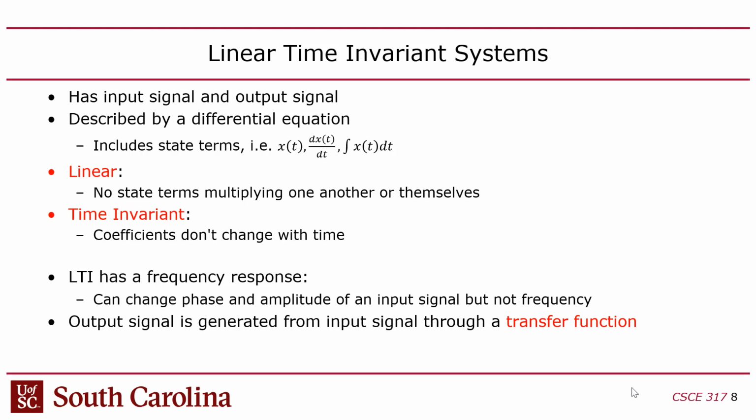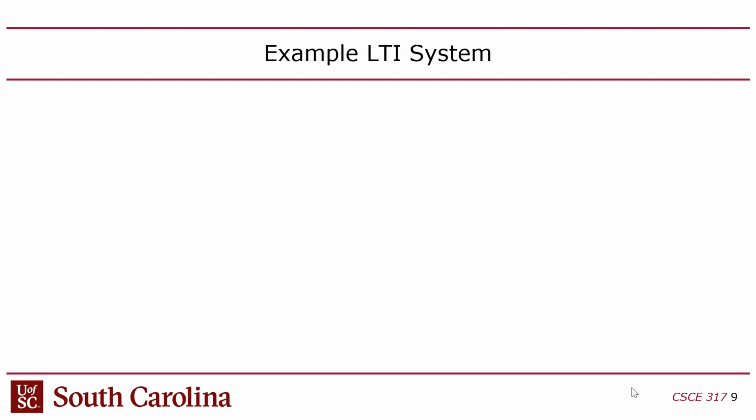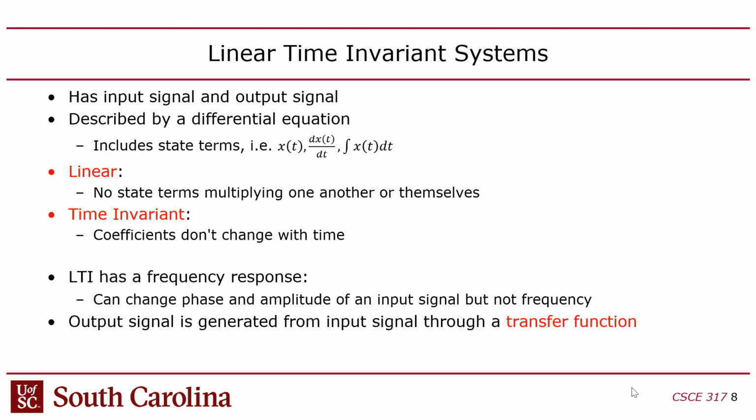The strange thing about this is that you might say, well, wait a minute, can you do nonlinear time invariant systems? Is that possible? They exist, but there's no good way to do analysis and design with nonlinear systems. All this S-domain stuff that we're doing is designed for these linear LTIs, right? Now, you might say, well, wait a second, the motor design from Lab 4, is that an LTI?